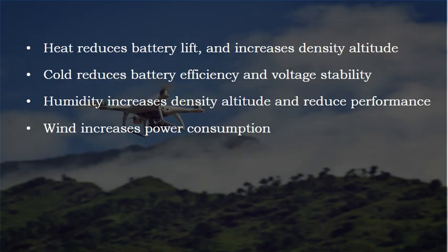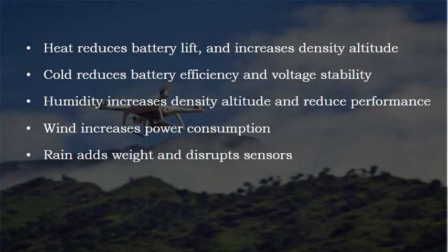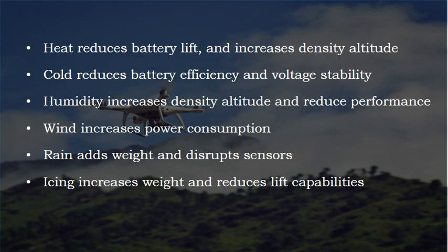Wind increases power consumption to maintain position. Rain adds weight and disrupts sensors. Many drone manufacturers' operating manuals recommend not flying in the rain. And icing dangerously increases weight and significantly reduces lift capabilities.